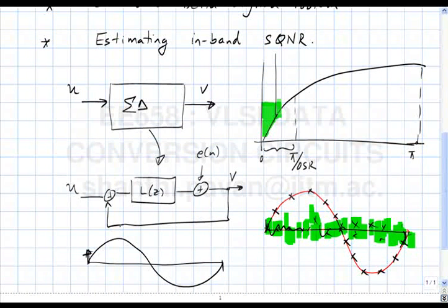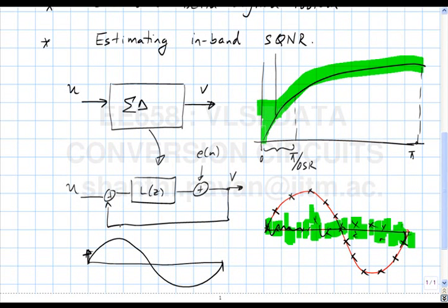noise spectral density. The component of the noise spectral density at DC must be 0, correct? At very low frequencies it must go up as omega cubed in this case, not omega cubed, omega to the power 6. If it's a third order modulator, the spectral density is shaped by NTF squared, so it must go as omega to the power 6. So at low frequencies you expect the noise spectral density to go to 0. Is that clear? But because of the way you are computing the Fourier series, there are discontinuities at the edges of the data record, which is equivalent to adding impulses. You will not see the spectrum plummeting to 0, you will see something flat. So you will see something like this and then something which flattens off and does not go to 0.